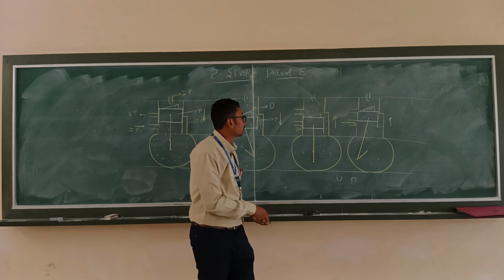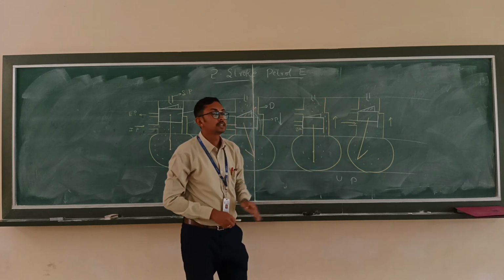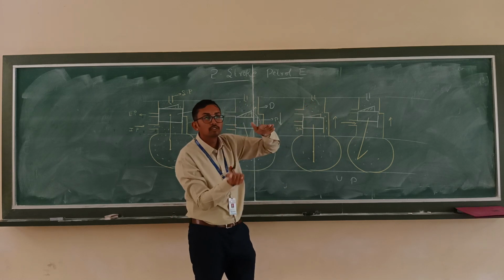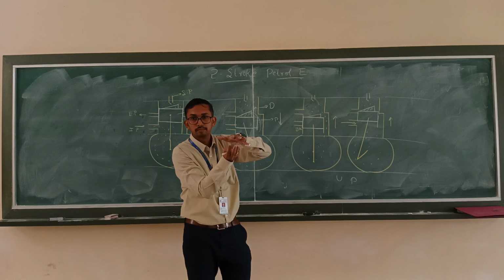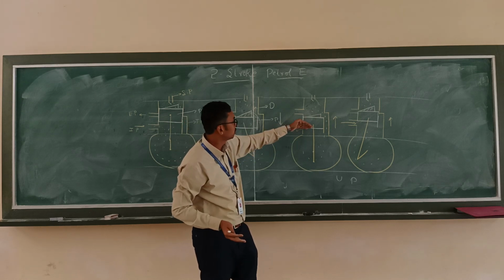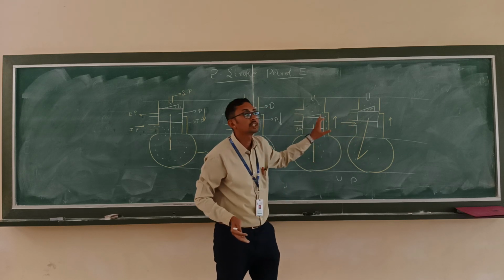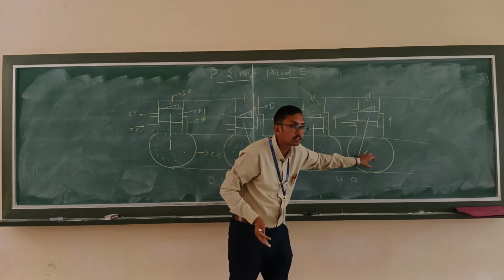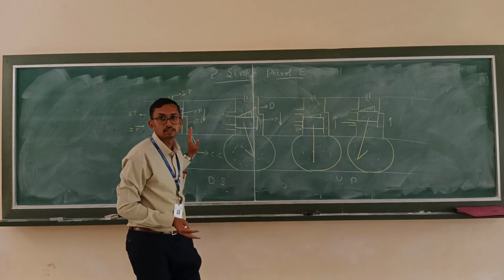Whatever air fuel mixture is present in the cylinder will be compressed to very high pressure and temperature. In the meantime, it is going to open the inlet port. The fresh air fuel mixture enters the crankcase, and the cycle repeats.